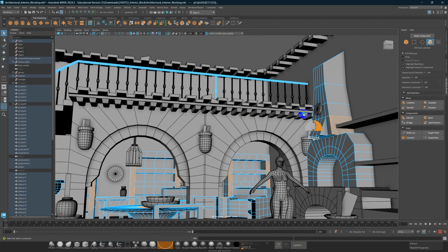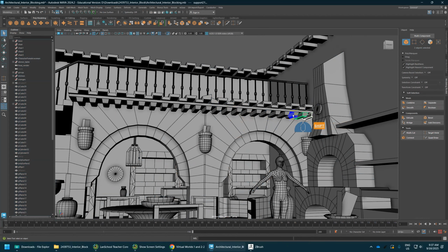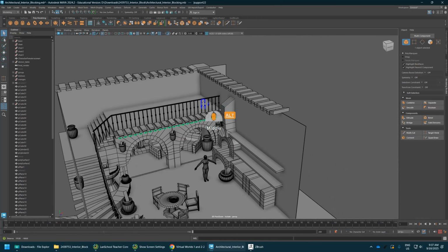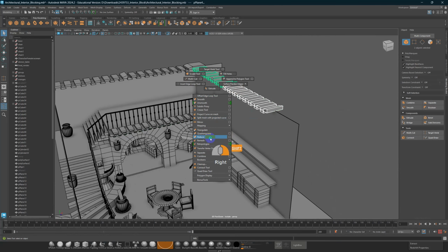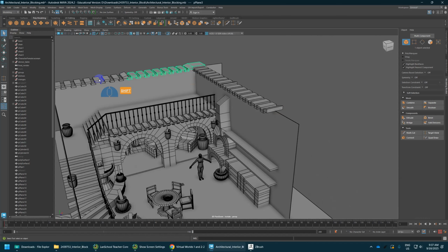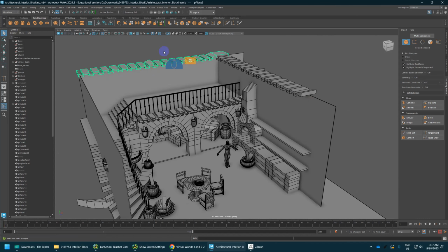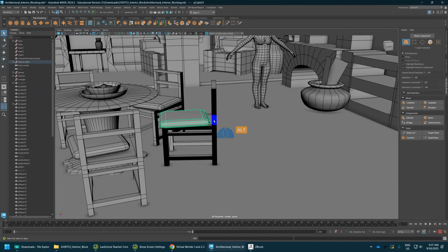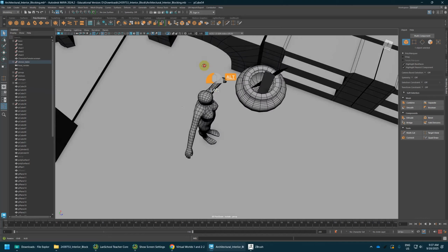The other thing, as I was mentioning, is these objects. You can combine these for ease of organization, sculpting, that sort of thing. They're not labeled, so that makes it hard to go in and grab them from the outliner, but shift, right click, combine. That sort of thing just makes life a bit easier, I find. By the way, if you're doing this a lot, you can just hit G, it repeats the last command. Let's say if you have a chair, it's made up of way too many parts. This one's fine for now.